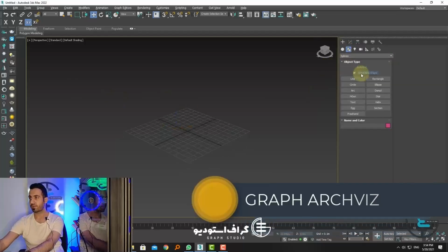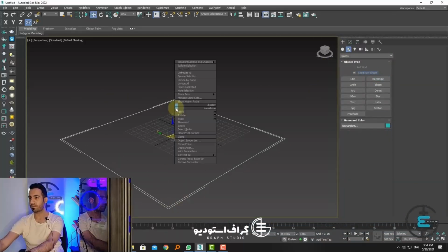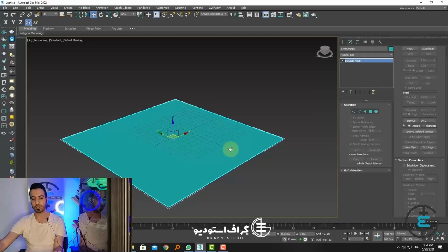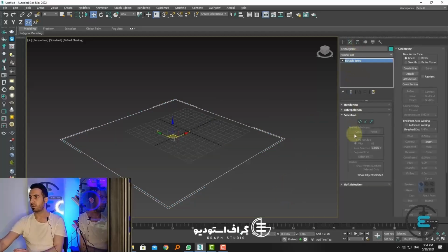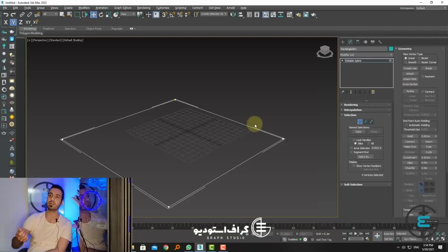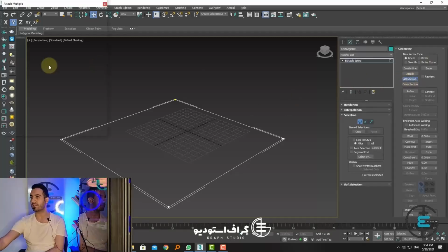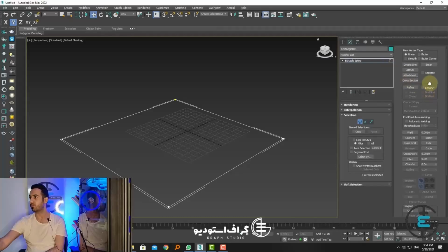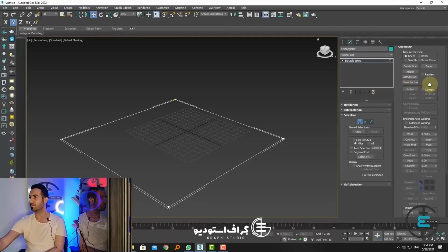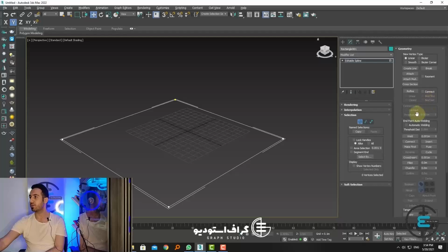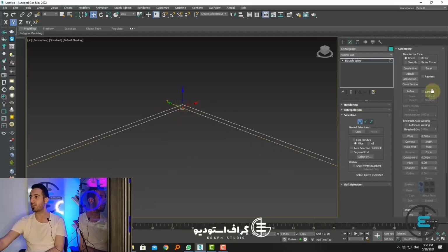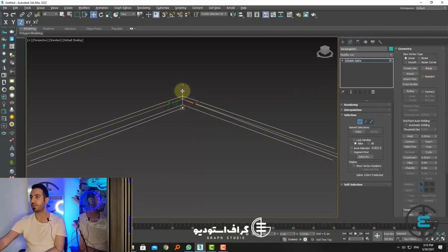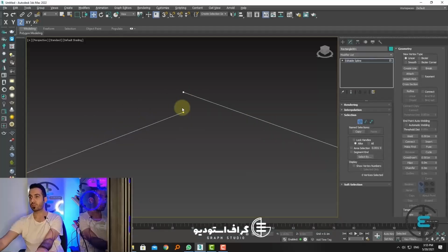Here, the break option, as it was in Edit Poly, is also here. These are now welded together. If I select it and press break, it is no longer welded together. You see guys, if you press Shift and G, this highlight and the frame they have drawn around these go away. If this bothers you, be sure to turn it off. Shift and G. These we have now broken. And in order to weld them together, we bring them as close as possible and press weld, and this is now welded. Our connect option, now in these vertex states, I don't use connect much.